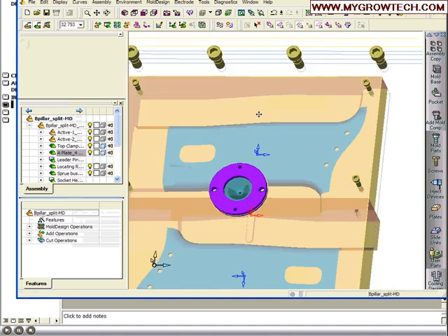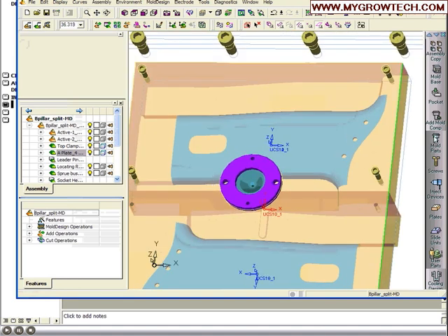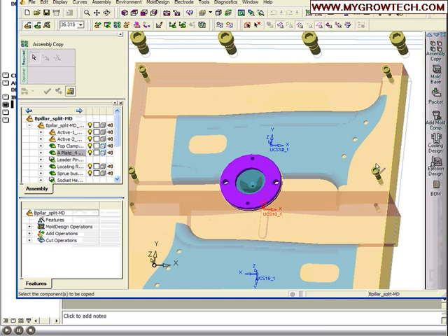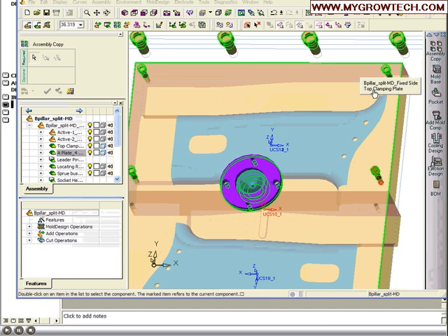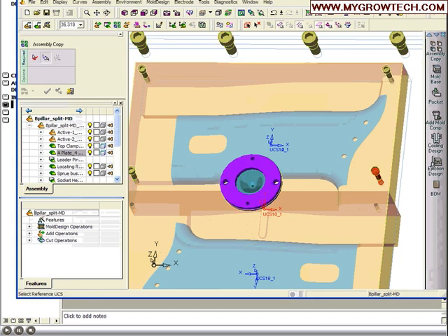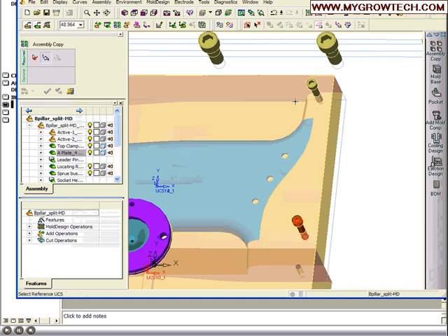Build those screws in, and watch what happens. You'll see how it builds a hole around the screw. It puts the drill and counterbore into the top clamp plate, and then threads and taps into the insert. What you do to one component or one insert cavity location, you can do to the rest.